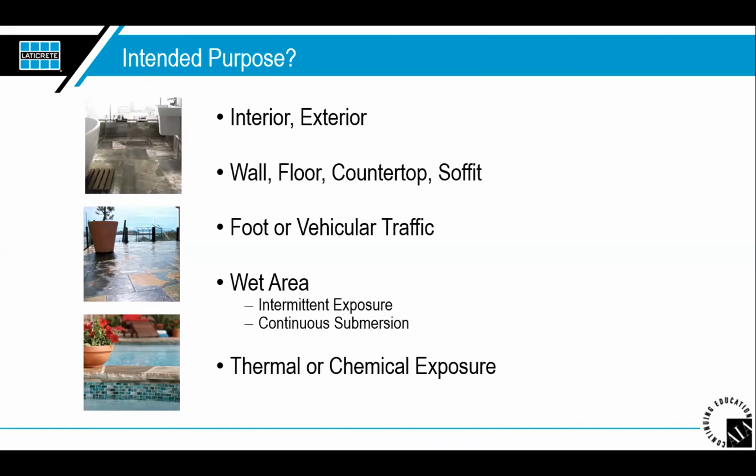We're treating the interior applications, and we're going to get to movement joints in a few slides, because they're interior and we feel that they're climate controlled. We're putting the movement joints about every 20 feet, for example, for tile installation to prevent tenting and cracking of the grout and the tile. And in reality, it's sitting next to floor-to-ceiling windows that stretch an entire section of the building.